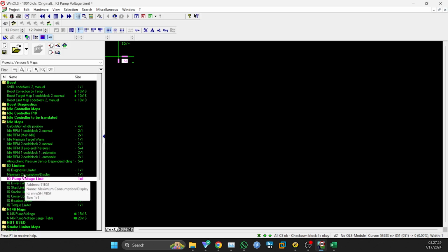But now we're running larger injectors. Maybe we're running an 11 millimeter pump, which really doesn't matter. But let's say we're running an 11 millimeter pump. We'll change our pump voltages. What most people do that I've seen, including Mr. Stevenson, is you change this to whatever you think the theoretical limit could possibly be.